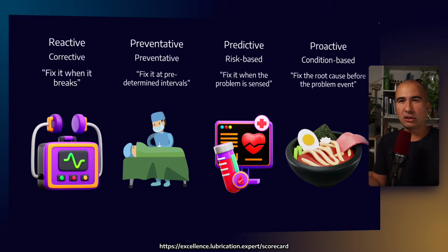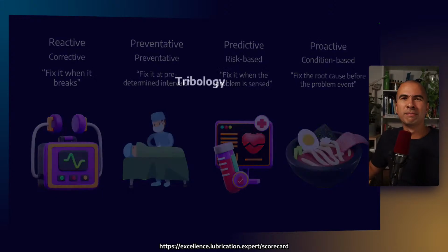It doesn't make sense to do oil analysis on all of them. It doesn't make sense to do maintenance on all of them. What it makes sense to do is wait until they fail because we have so much redundancy and we just keep lots of spares, right, in storage. So that would be an example where reactive maintenance can be the correct answer in certain circumstances.